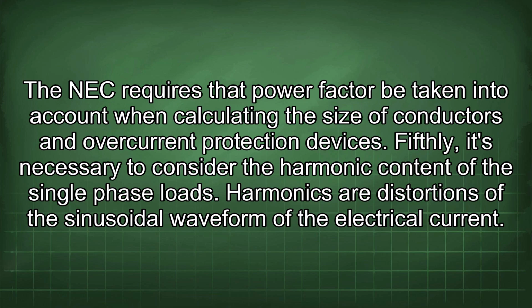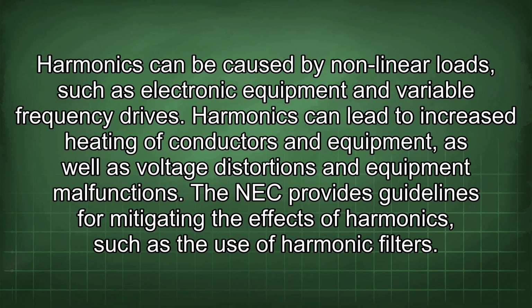Fifthly, it's necessary to consider the harmonic content of the single-phase loads. Harmonics are distortions of the sinusoidal waveform of the electrical current. Harmonics can be caused by nonlinear loads, such as electronic equipment and variable frequency drives. Harmonics can lead to increased heating of conductors and equipment, as well as voltage distortions and equipment malfunctions. The NEC provides guidelines for mitigating the effects of harmonics, such as the use of harmonic filters.